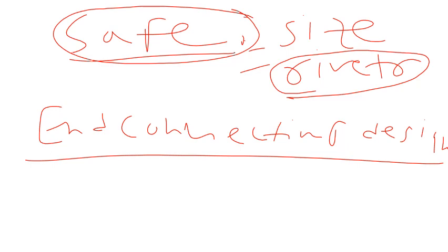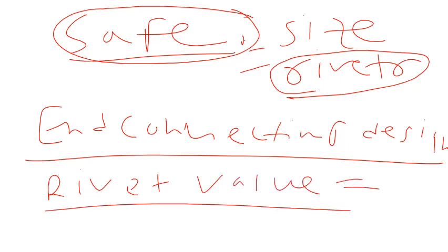For that again you have to go to chapter number 2 on the fasteners. So for that, first of all we need to find out the rivet value, right? Rivet value is nothing but the minimum safe force transferred by the rivets. How to determine that? This will be in different modes of failure. So to determine the rivet value, first of all consider rivets in double shear.